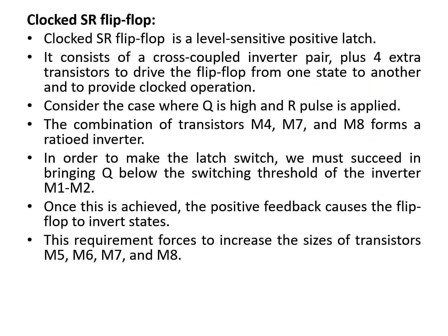Clocked SR flip-flop. A clocked SR flip-flop is a level-sensitive positive latch. It consists of a cross-coupled inverter pair along with 4 extra transistors to drive the flip-flop from one state to another and to provide a clock operation.